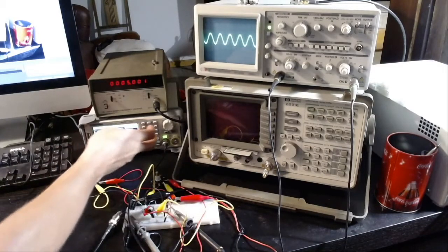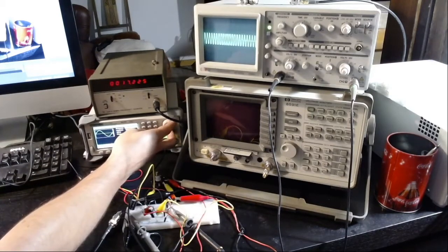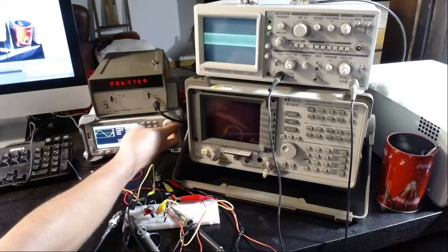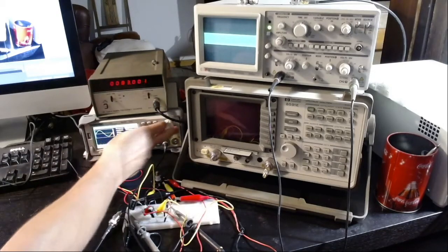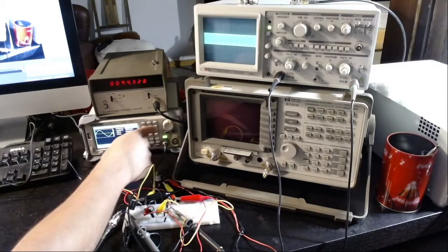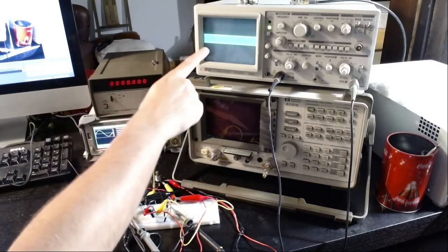And if I now change the frequencies, let me modify it, we get 30 kilohertz. As you can see, the amplitude of the input is not changing when the frequency changes. So this is a sign that indeed the input impedance of the amplifier is 50 ohm. Otherwise it would change with frequency. Let me put 5 megahertz, for example, and as you can see, it was slightly attenuated.